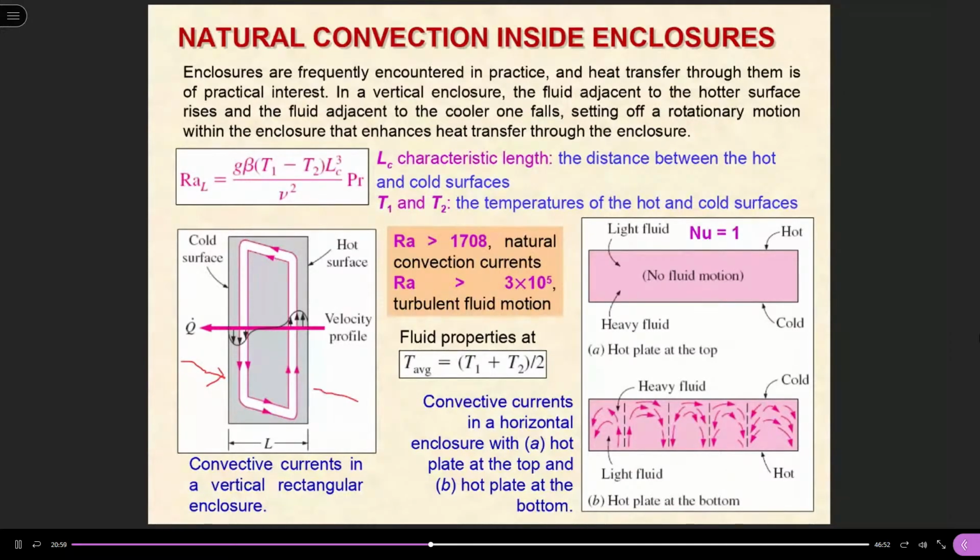One other technique is so-called double glazing. As we talked about before, instead of using one layer of window, you have a double layer of glass. Then there will be a so-called cavity inside, a very thin layer of air between the glasses. For example, inside you are keeping your house warm, outside temperature is low, you still have some heat loss. Theoretically, you'll have a heat transfer coefficient from this surface to the air, then from the air to this side.